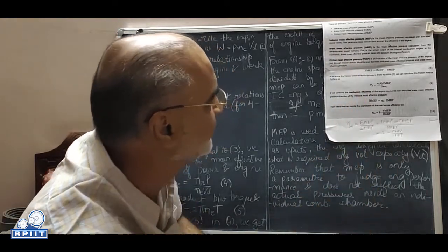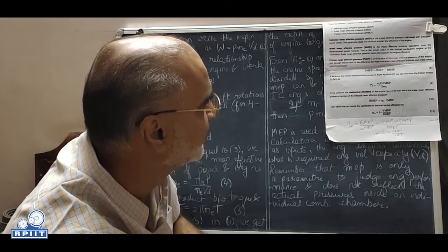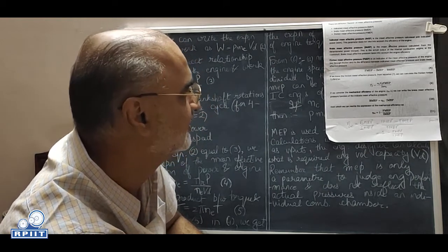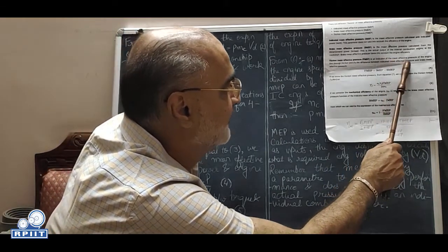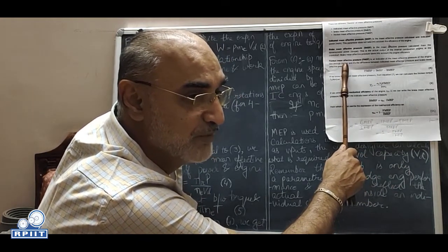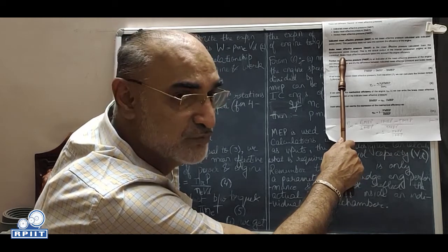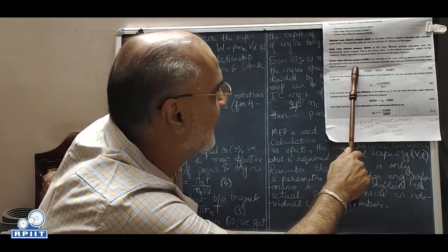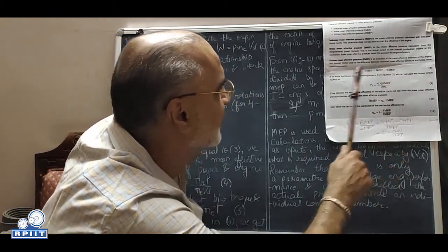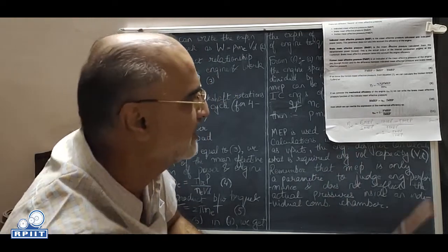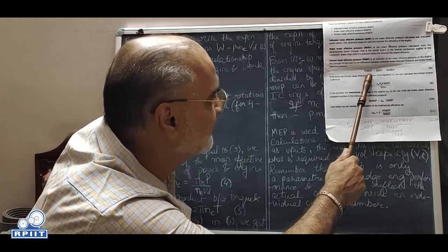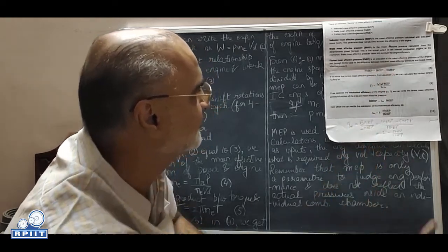Frictional mean effective pressure is an indicator of the mean effective pressure of the engine lost through friction. There are frictional losses: the piston is moving up and down, and there are other components moving. It is the difference between indicated mean effective pressure and brake mean effective pressure. Indicated is always higher. So FMEP is equal to IMEP minus BMEP.